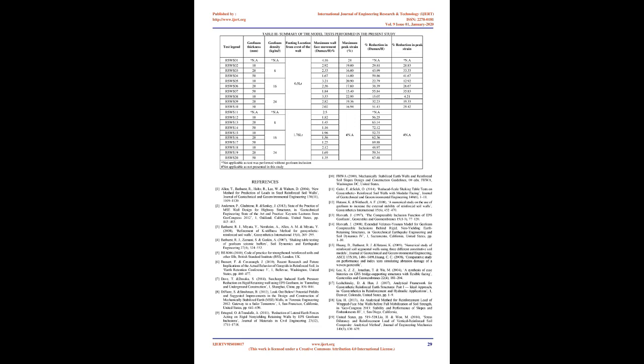Also, the geofoam panel acts as a cushion behind the reinforced zone and distributes the load evenly on the reinforced soil, due to which the wall face movements tend to be similar over the elevation of the reinforced soil wall.